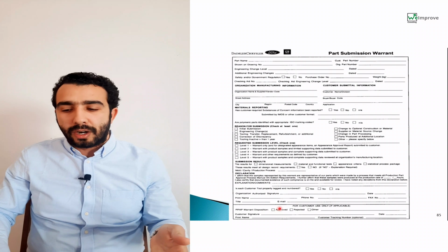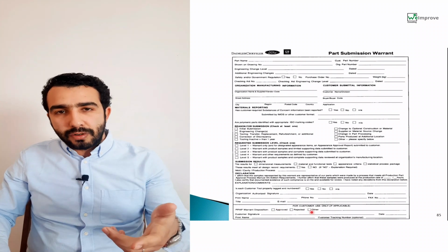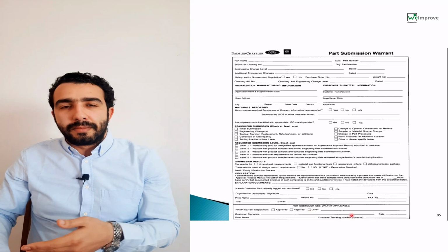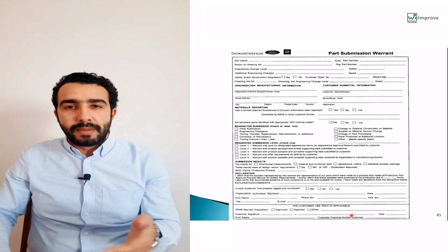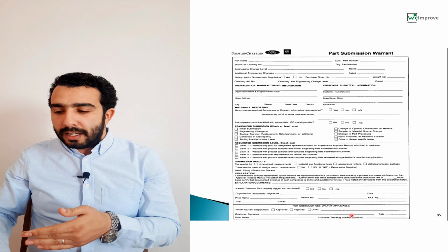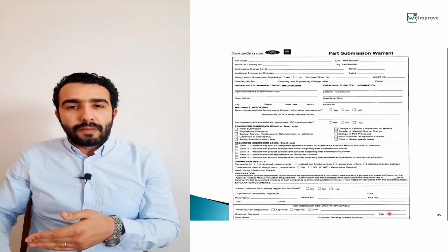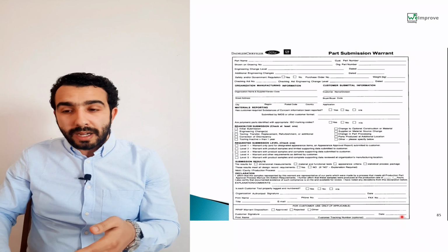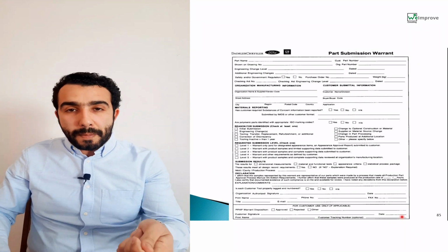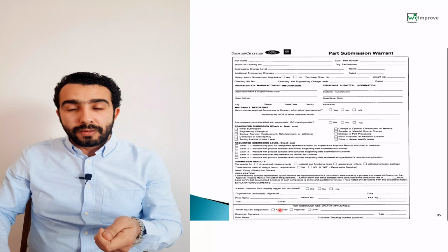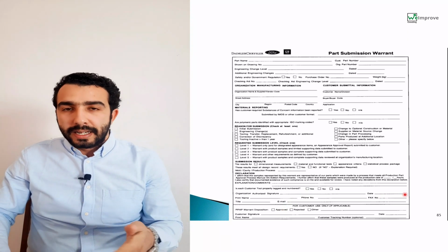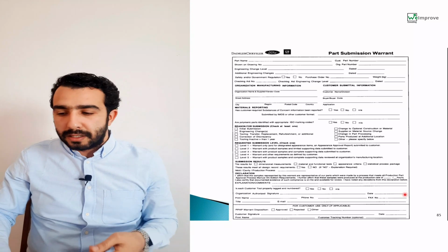Then you have to push them again to give you the last status, which is approved. So always make sure you have the approval. If they give you, for example, the status interim, in general interim is a maximum of 6 months. So if the customer puts the expiry date of the interim, for example after 6 months, and you didn't submit a new PPAP and you didn't get the approval, it means the previous approval is already expired and you are not allowed to ship the parts to your customer.